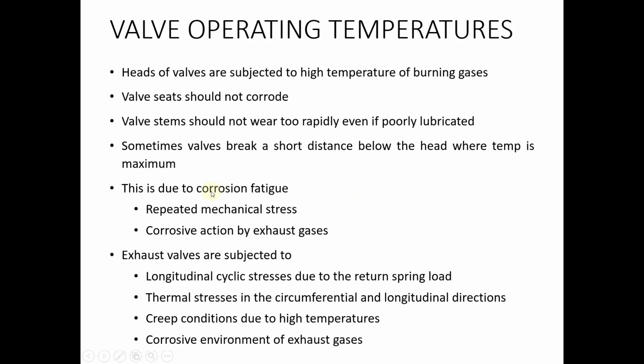Now, at high temperatures, there is a phenomenon known as corrosion fatigue, due to the high temperatures and stresses experienced. So during operation, sometimes a valve may break a small distance below the head, where the temperature is maximum, and this is due to corrosion fatigue. Corrosion fatigue occurs due to repeated mechanical stress.